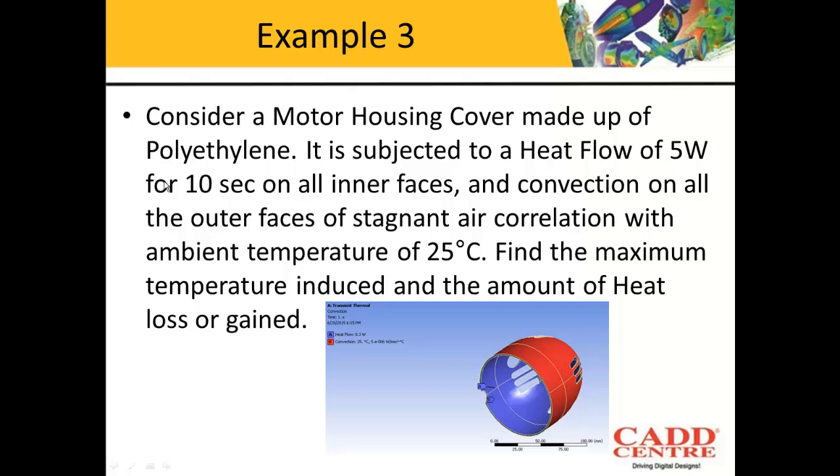Now in this case, if you notice that the load, that is the heat flow of 5 watt, is acting on the body for 10 seconds. That means time is coming into picture over here in this example. So this is a transient thermal analysis that we have to perform. Okay. So now let us understand what is transient thermal analysis.